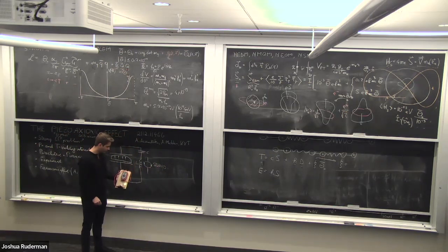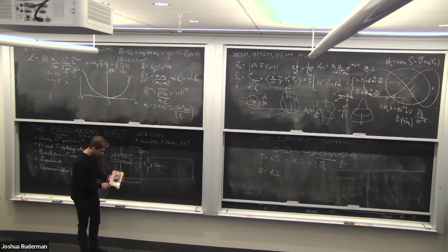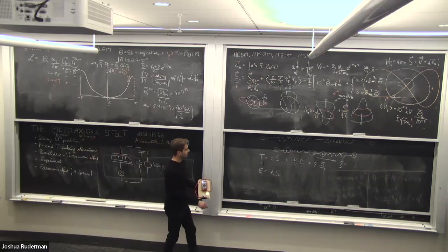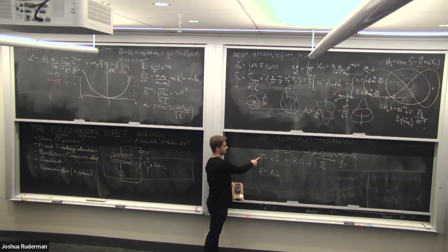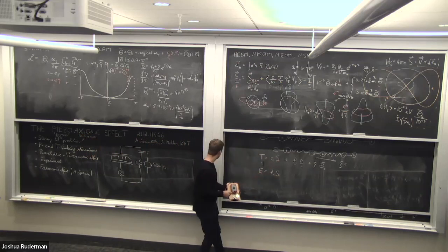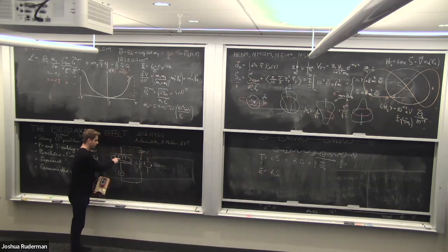This is a voltmeter. This is a tiny piezoelectric disc. If I introduce some stress, or press on it, I generate a strain, and the strain gives me an electric field between the opposing plates here, which I can then read out with the SQUID or a voltmeter.